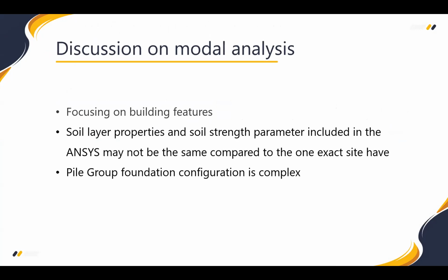But it is still necessary to review some of the field assumptions and modeling decisions. Our project focuses entirely on modeling and sketching the external building features, but our team believes that the interior structural components may significantly impact the fundamental period of the building. So we computed the mass density of the building by using the total mass of the structure divided by the total volume of the structure.